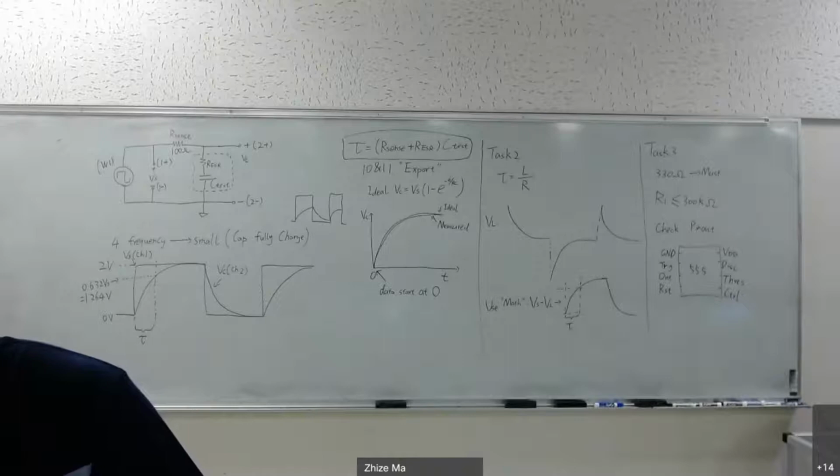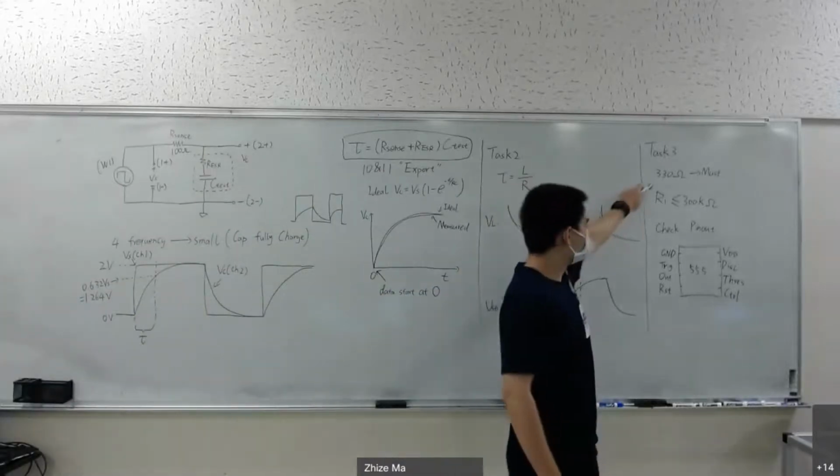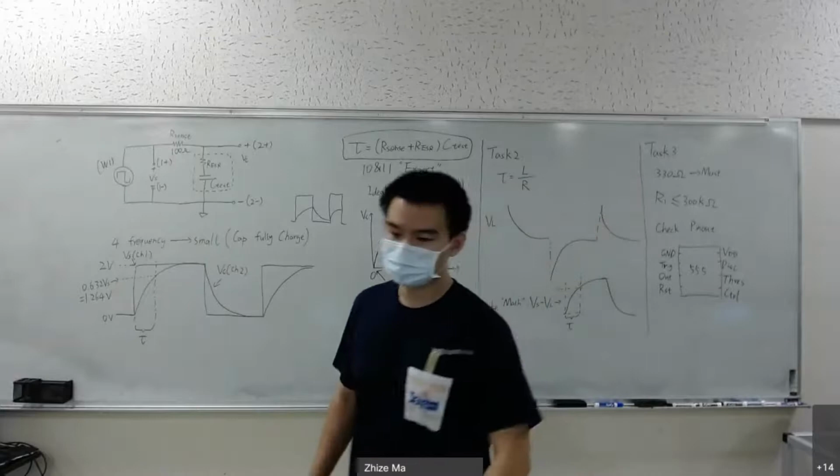Maybe I can show you what it looks like later. And the component at the far left side is an LED, and the LED does not have any resistance. So to make sure you don't short your output, you must have a 313 ohm resistor before the LED.